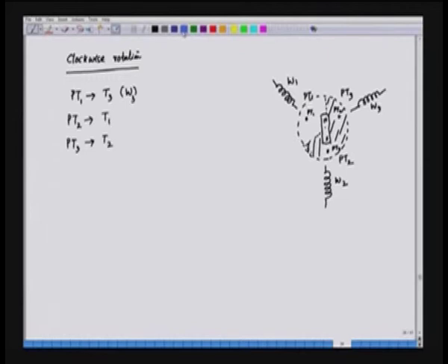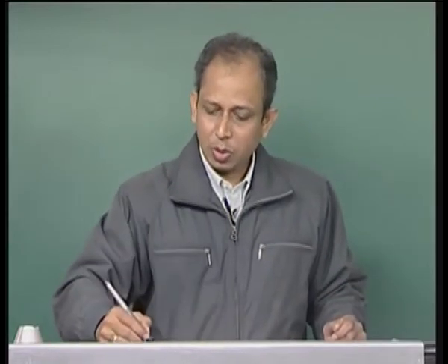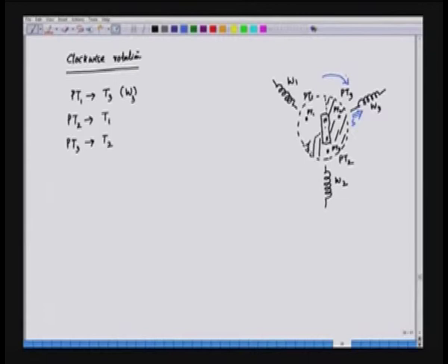So, we will have a south pole here. So, when we have a south pole in this case, this north pole is attracted towards the south pole. So, the rotation will be in the clockwise direction. So, the rotor will rotate in the clockwise direction like this. Similarly, PT3 is feeding W2. So, the field will be moving from this position to this position and then after some time the field will be moving to W1 to this position, and hence we have a continuous rotation which is in the clockwise direction. Now, this is a simple principle of a brushless DC motor.